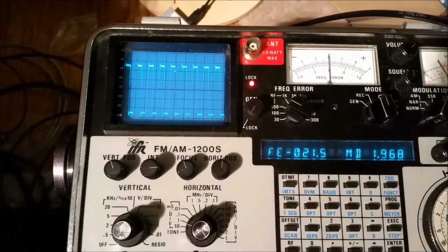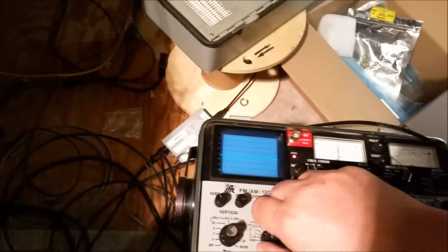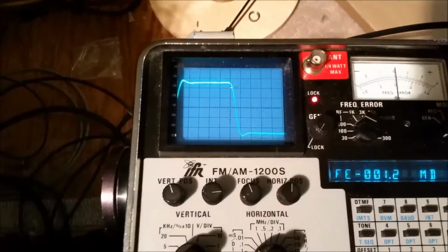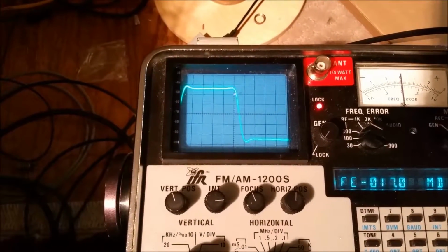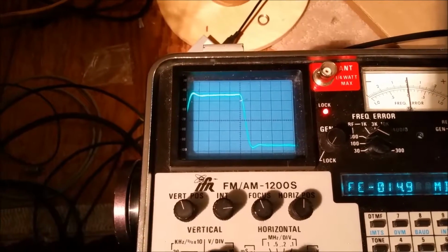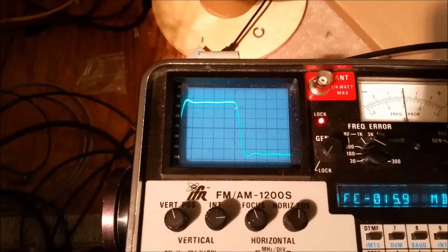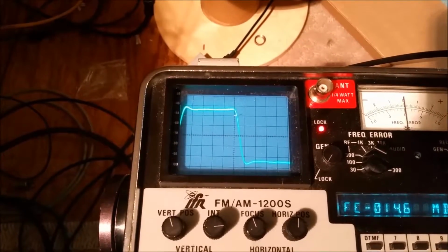I really need to buy a better camera. I have another camera on a tripod. So okay, we're on there. So now if I hit transmit, there's my square wave. It's square enough. Square enough. Got a little bit of a ring to it, a little tiny bit, but I think that's due to my probe, the compensation on my probe. So, can't ask for better than that.